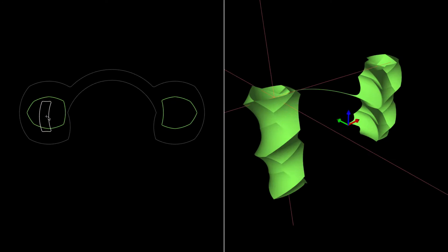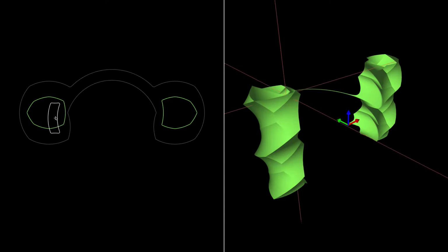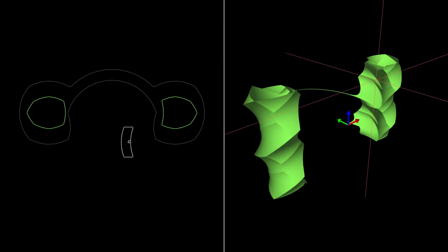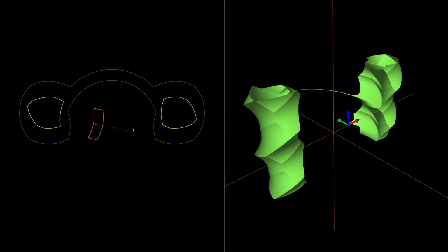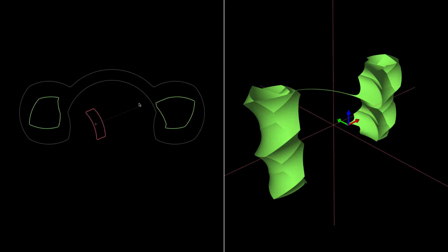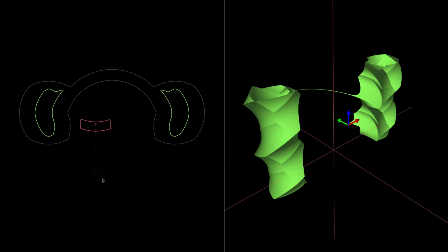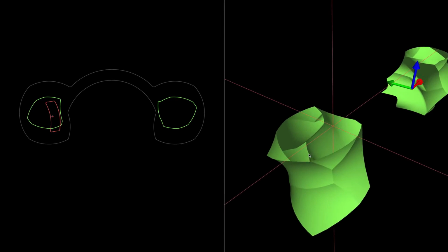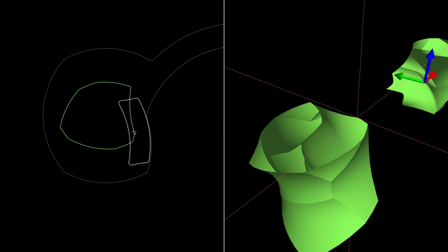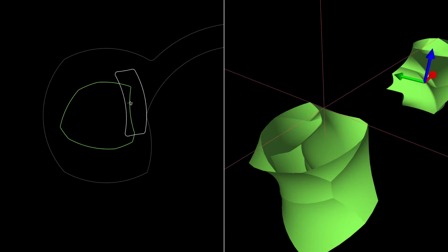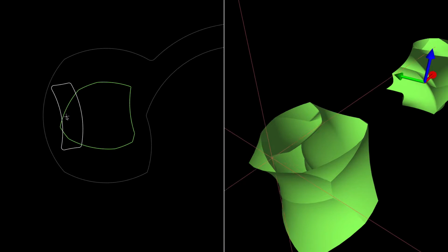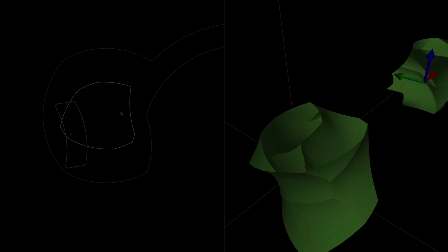The robot, which is a shape in 2D, becomes a point configuration in 3D. This configuration is its x, y, theta coordinates. The robot configuration is visualized by the intersection of the 3 red lines. Notice how the 2D robot is just touching the obstacle surface as this point makes contact with the green surface in 3D. As long as the robot is on or inside the 3D surface, the 2D robot is not colliding with the obstacle.